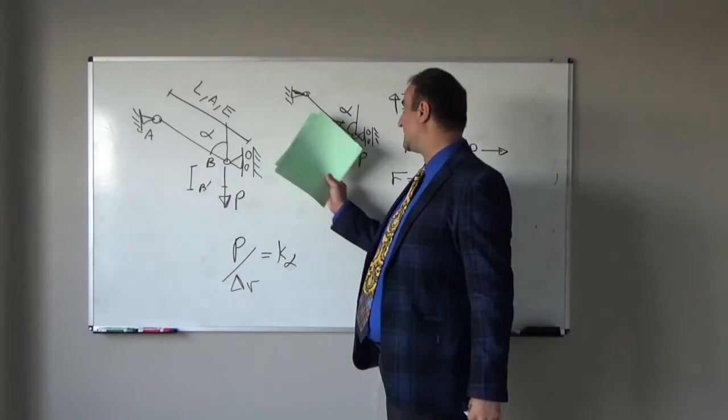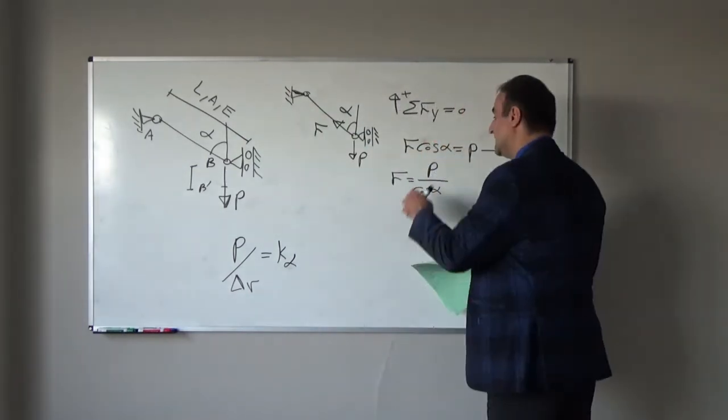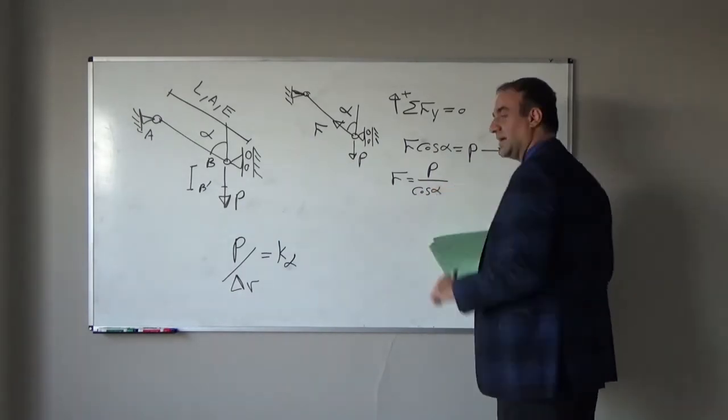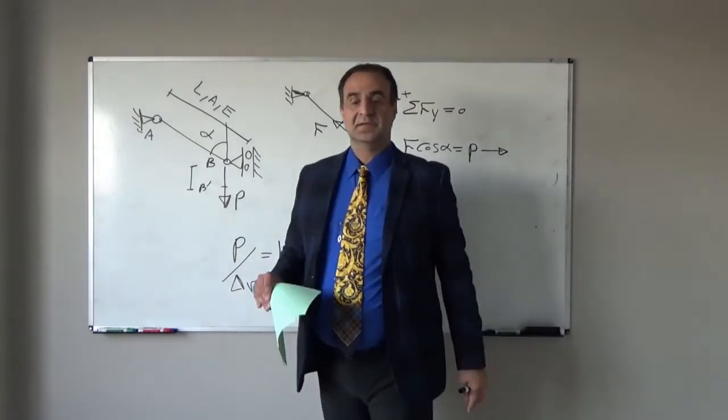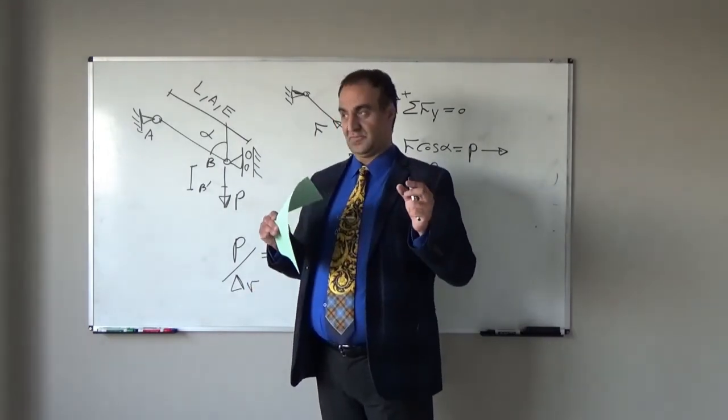So the internal force inside this member will be the external load divided by cosine alpha. Now we know the internal force of that member.